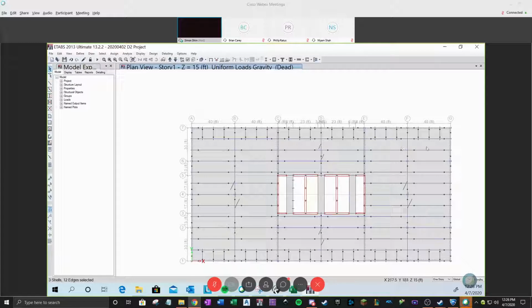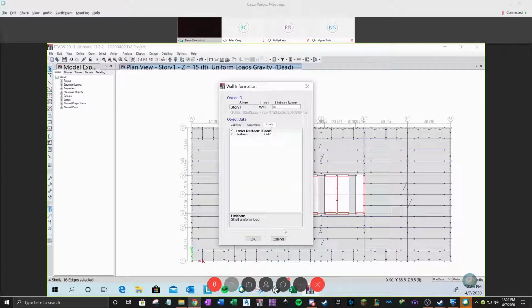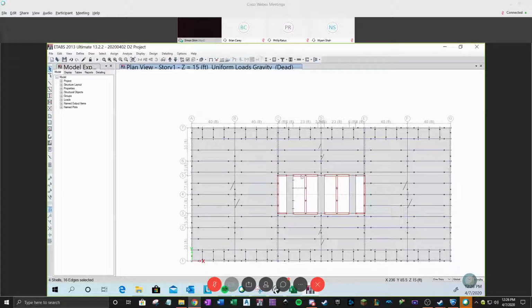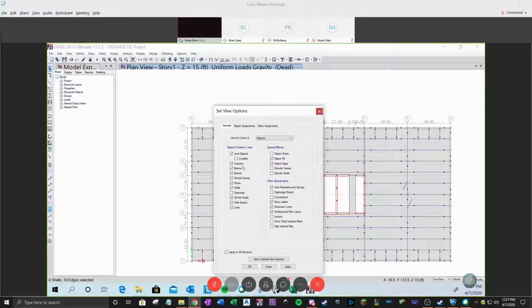So all the slabs now have 20 PSF superimposed dead load and 100 PSF live load. Corridor for now, let me see. Corridor doesn't have a live load for now. You could just ignore it, or you could add it later. But for now, today's class is more focused on composite floor framing design. I'll just keep loads outside of the core.